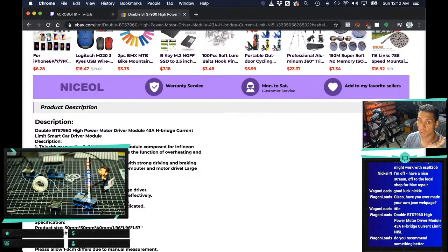So you have two choices. As you know, the ESP8266's operating voltage is 3v3. You can shift those signals up with one of those little 74HC245 chips, level shifters, or you can just try your luck.